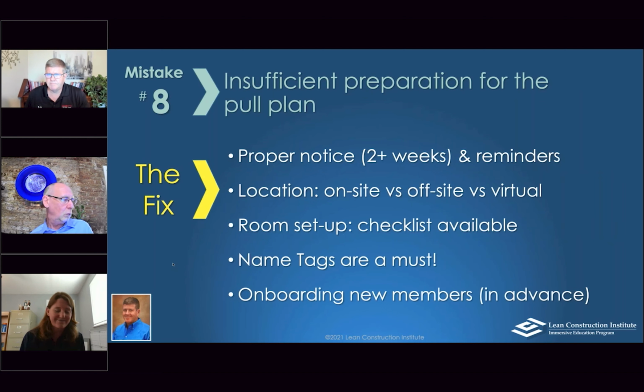All right. Next. Okay, so I'll take it from here, at least for the short term. Mistake number 8, insufficient preparation for the pull plan. A lot of times you hear about pull plans that didn't go well. Either they didn't have the right people in the room, or they sent somebody that didn't know anything about the job, and you just don't get the real value out of it. A lot of times it becomes wasted time, so I relate that back to the preparation.